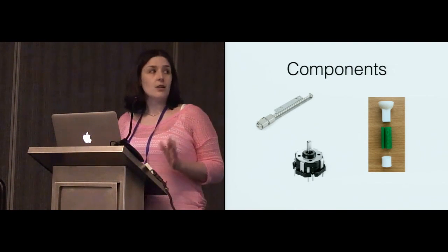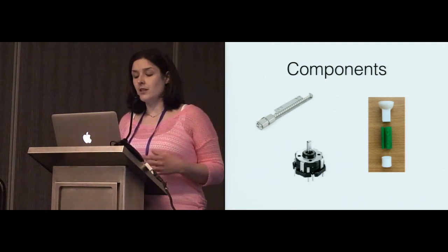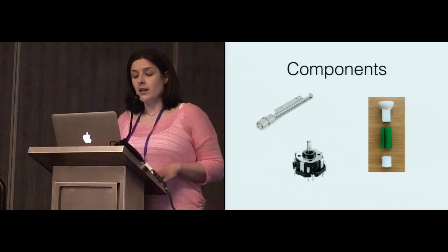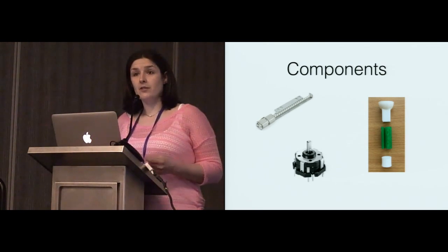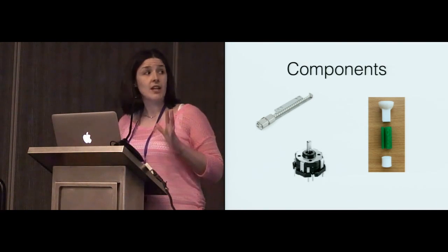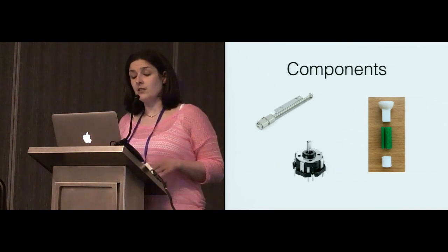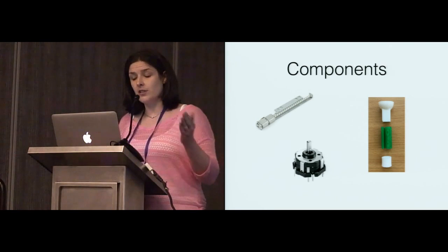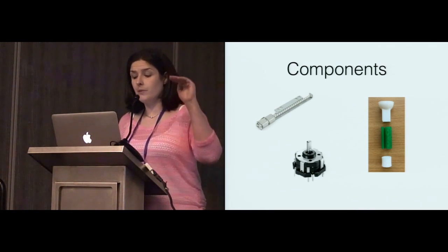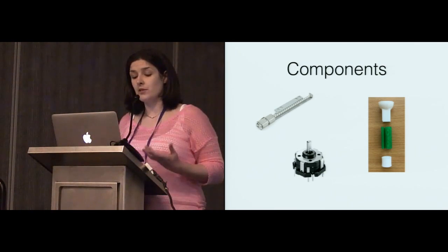We tried quite a few different iterations of doing this before settling on this design. I won't bother you with the details here, but I can say that in our final prototype, each stencil consisted of a micro stepper motor, which we harvested from laptop CD drives, which facilitates the up and down movement of the rods, a navigation switch, which facilitates the rotation and side-to-side movements of each stencil, and some 3D printed components to form the top of each stencil and allow proper attachment to the electrical components.